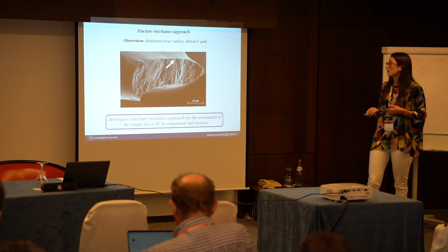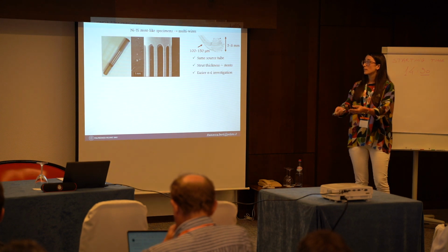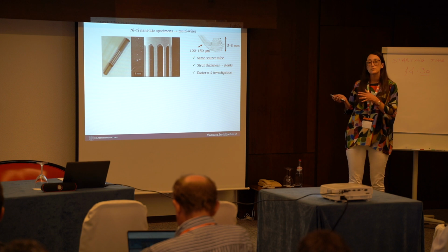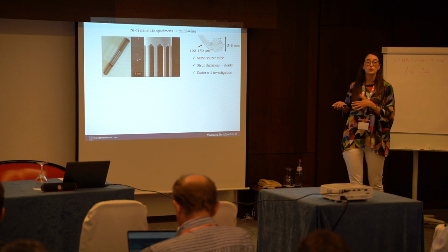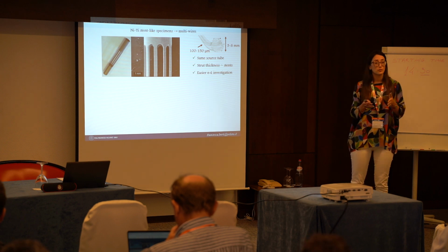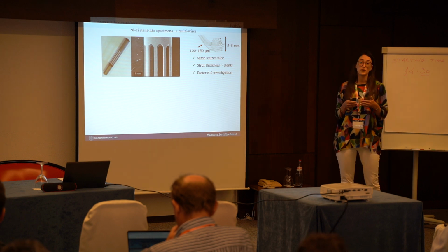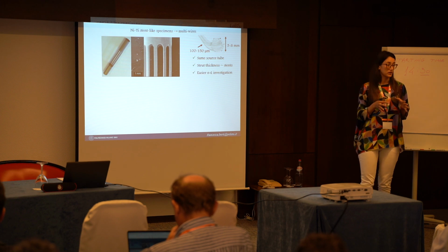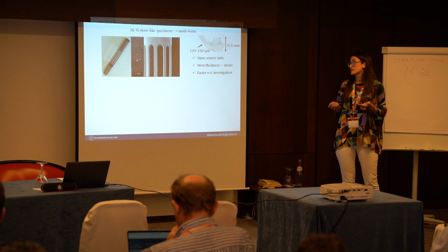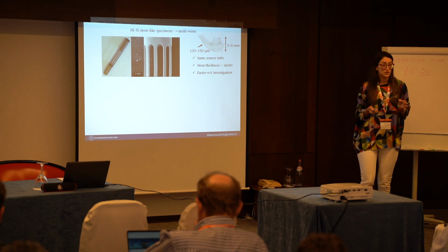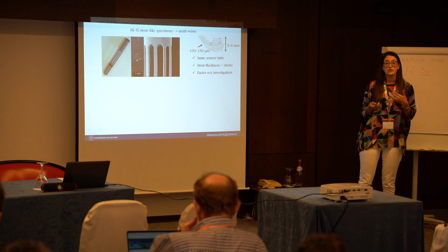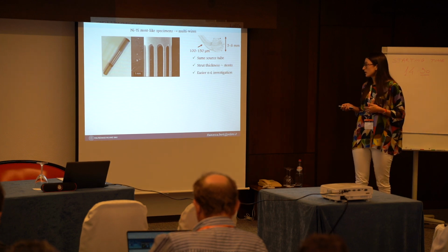So I started from a simplified geometry, so you can see I'm not studying the stent, but a stent-like specimen. This is a multi-wire specimen that is laser cut from the same source tube as the stent and underwent the same thermomechanical treatment to guarantee the same material. Moreover, these wires have the same dimensions as the stent struts, but their simple geometry allows an easier stress-strain evaluation.